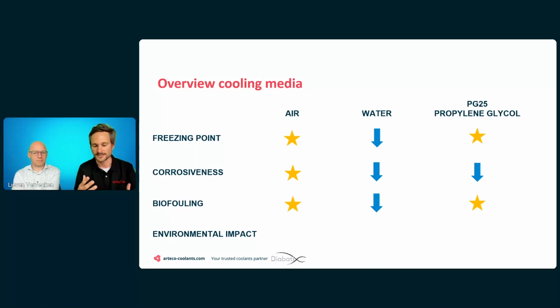The biofouling is the growth of microorganisms in the cooling system. It's a huge concern today. It's less or no risk with air-cooled systems, but it's a big concern for water-cooled systems because the temperatures that the cooling systems are running at for data centers is in a range that allows microorganisms to proliferate.